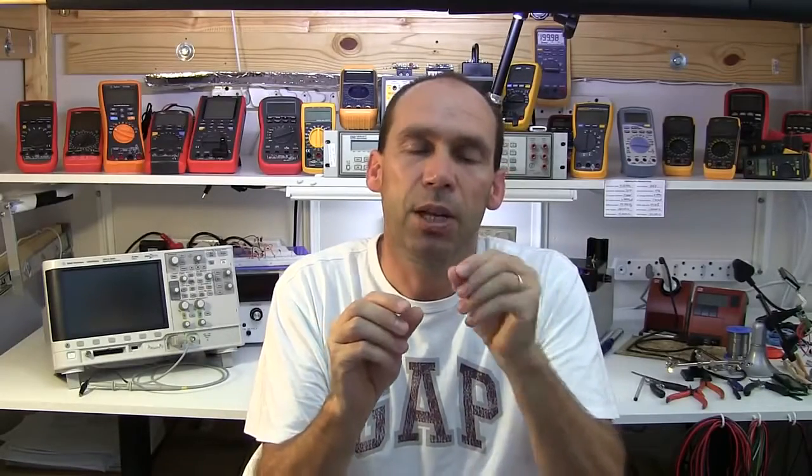The other thing I mentioned there was that a solar powered geyser can act like a storage battery. In summer in particular, you can have a few days of overcast weather, and if you've got a good efficient heating system which can take your water up to 70, 80, 90 degrees, you can use a thermostatic valve. That thermostatic valve, or tempering valve as it's sometimes known, is actually legislated here in South Africa as a safety requirement. You preset the heat of the water that can come out of it.